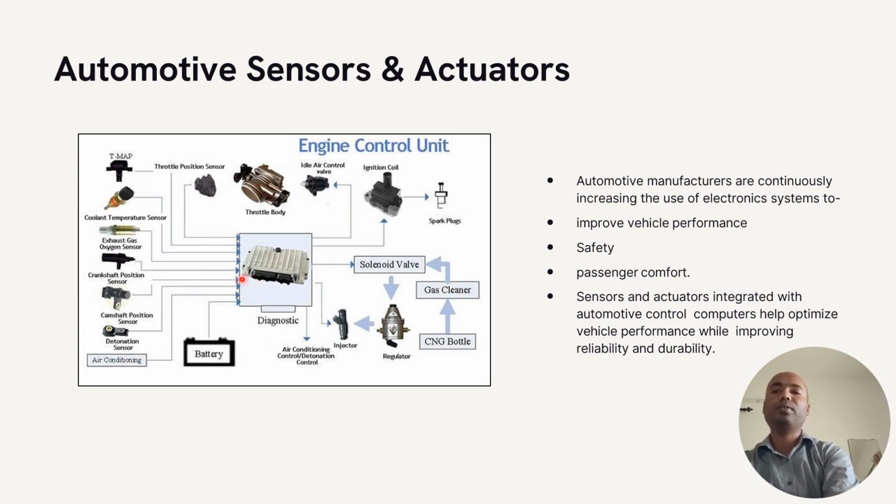Based on that embedded coding, it receives the signals from the sensors and performs signal processing. It converts the signals from the sensors, whether analog, digital or power supply, into machine code, zeros and ones. Based on these zeros and ones, the ECU programs run, and based on that, it creates an output. These outputs are sent to the respective actuators.